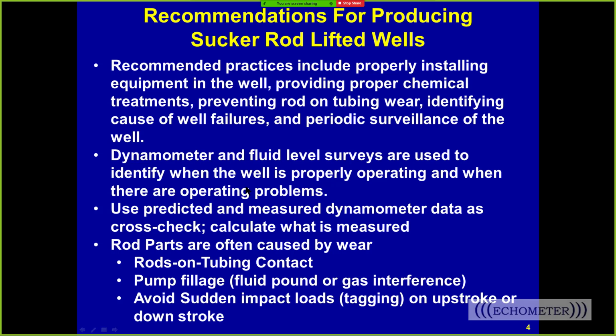We use a fluid level and a dynamometer survey to understand that the well is operating properly, and if there are any problems, we hopefully will see those and identify those and prevent them from becoming a problem in operating the well. We talked about Q-Rod recently, in one of the Ask Echometer presentations, and that allows you to overlay your measured data with your predicted data, and they should match up.